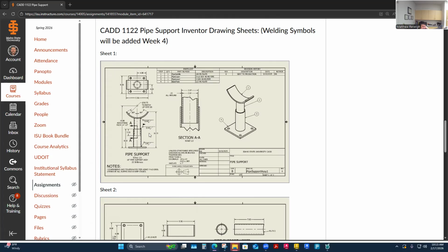I do have quite a few assembly details. I got all my weld symbols on here. Got a weld all the way around in the field, 3/16 fillets, arrow sides, all a 1/4 inch fillet here though. I'm definitely showing that I'm 19 inches modeled, but I'm adjustable down to 14 1/4. Well, I'll just leave it there. Got my parts list here. I show some general overalls plus I call out some general notes here that I'm matching 10 1/4 inch ID pipe.